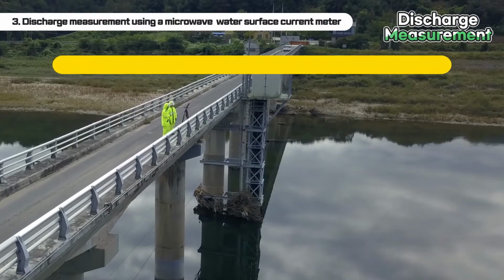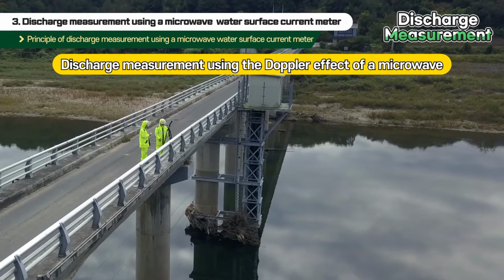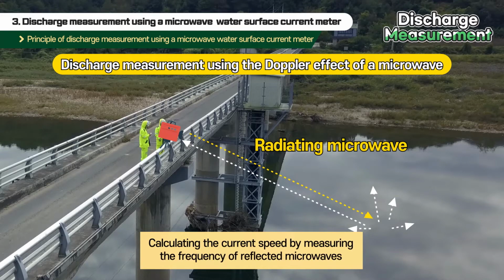Now, we will take a look at the third type of measurement device, a microwave water surface current meter. A microwave water surface current meter measures the current speed using the Doppler effect of the microwaves. When microwaves are radiated to the surface of the water, they are reflected on the surface of the water, and some of the reflected microwaves return to the antenna. The returned microwaves can be used to calculate the current by measuring the frequency generated by the Doppler effect due to the movement of the water surface.